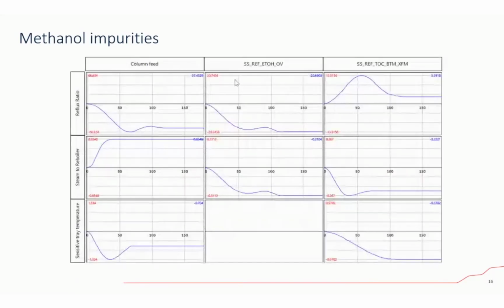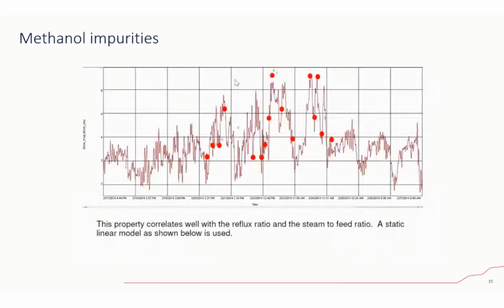And after we built the soft sensor, then we started finding the dynamic step response curves for each one of them. So just to give you an example of how the multivariable problem comes here, because you could say, okay, well, then it's simple. Then I put my soft sensor, right?